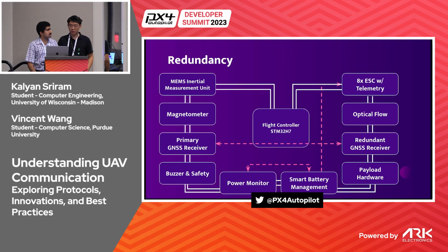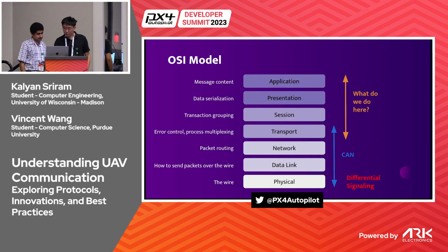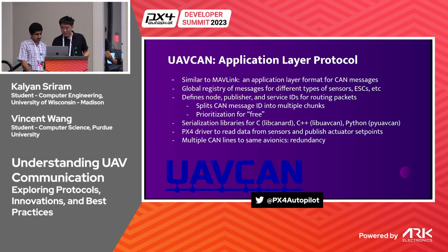You may also notice that this does create another failure mode. If the CAN bus itself got damaged, it could potentially take down multiple nodes in the chain. But we can mitigate that by adding a second redundant line that communicates the same data. So CAN provides a good hardware transport layer that can solve a lot of the problems we have from older technologies. However, we don't have an application layer standard for how it's used. So the message content still isn't standardized, so it's still not possible for the different nodes in a UAV ecosystem to interoperate effectively. So what can we do to solve this?